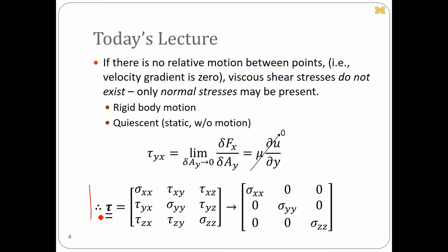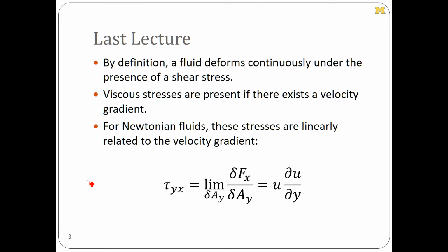So if I draw that thing that I just erased again, and if we measured the slope of this, then we would find that the shear stress acting on this wall is equal to mu times that slope.